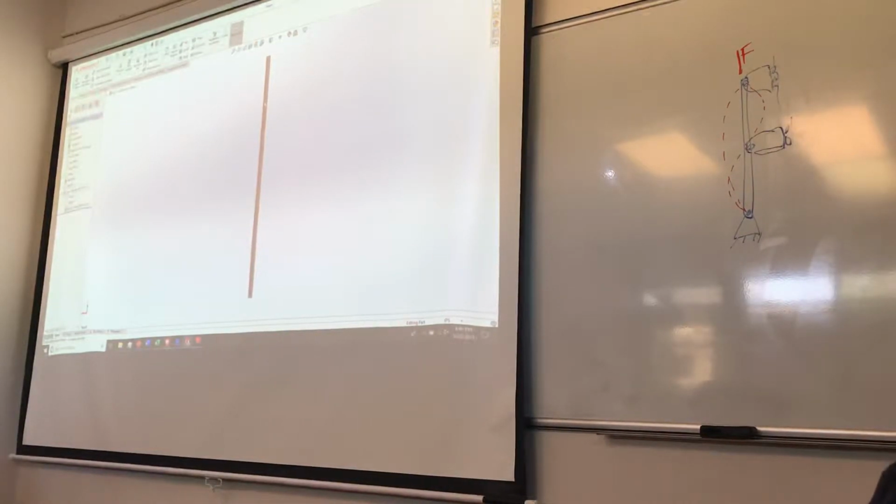If you go to insert weldment and add a new one, does that work? Yeah, I could probably do that, but then it'd get rid of the old one. You can hide that one and then just use the sketch again. Yeah, okay. Certainly can use the prior sketch. And then insert a new section.